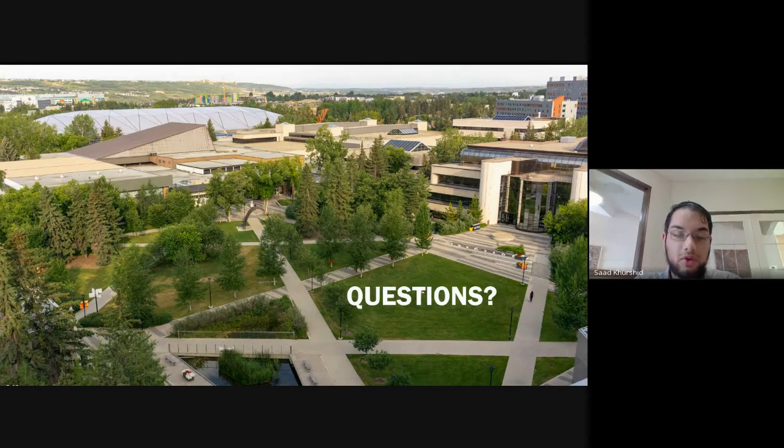The reason our traffic flows changed is because we assumed that people travel along a minimum societal cost path. That means in our case, because we improved the Brentwood path, we dropped its cost so much that it diverted people from other paths onto the Brentwood path. That's why the traffic flows increased on the Brentwood path. We assume the origin destination matrix will be exactly the same between now and the long-term plan. It's a bit of a conservative estimate of the societal benefits.